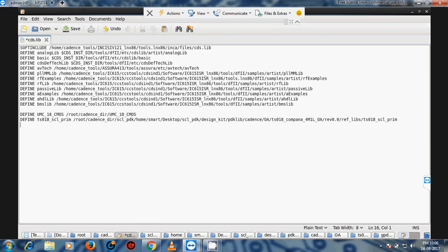So actually here I am including this file. So we use the command soft include or include, you can use either. This is equivalent to a link, hard link or soft link. If you are using soft include, it is equivalent to a soft link, and if you are using only include, then it will be equivalent to a hard link.